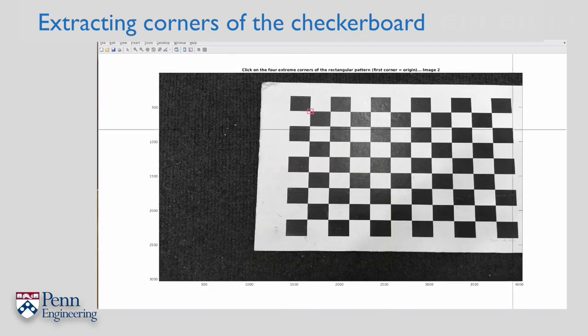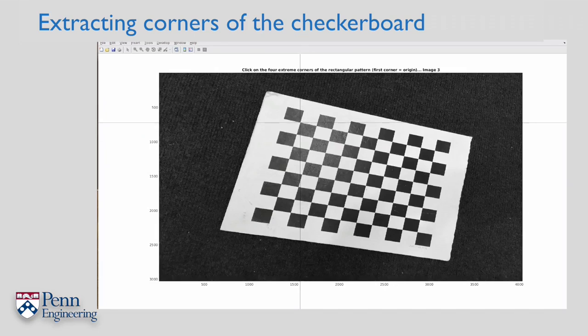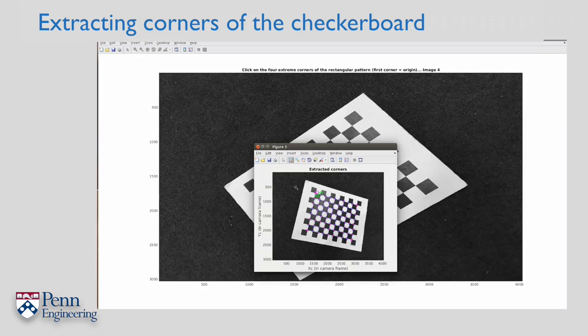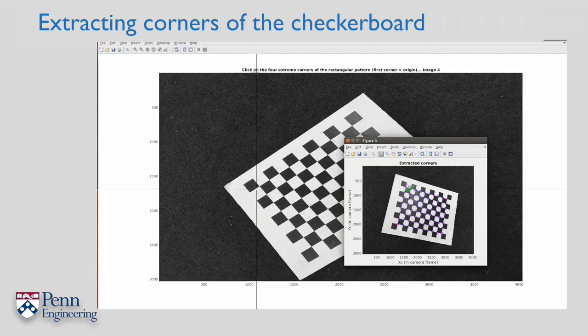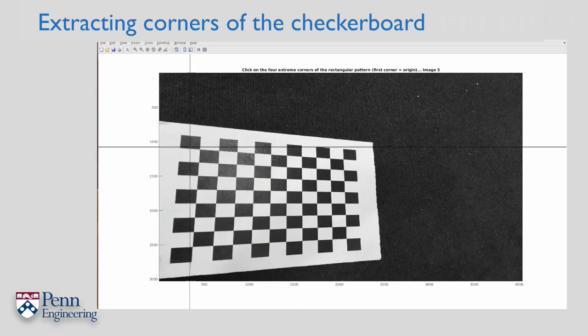The upper left point, the first one that we click, has always to be at the same position and visible. The other points can be, for example, shorter or less deep in the image. The images have to be taken from several viewpoints so that the checkerboard appears quite obliquely and varies in appearance in all the 10 images. If possible, not only rolling the image around the optical axis, but also tilting it and panning it.